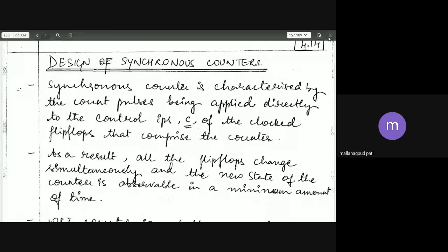See, in a JK flip-flop, in the case J equal to 1 and K equal to 1, the output will toggle. The output will toggle in the sense that whenever the process is over, it changes its state from low to high and high to low. If the pulse time is too long or extra, then the output does not look like simply high to low or low to high. In the whole period, it will change from high low, high low, high low. It acts as a continuous pulse triggering.